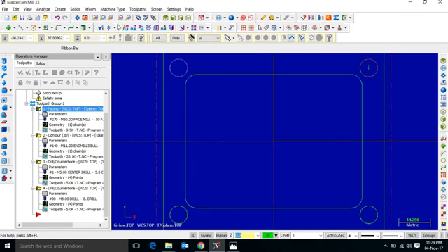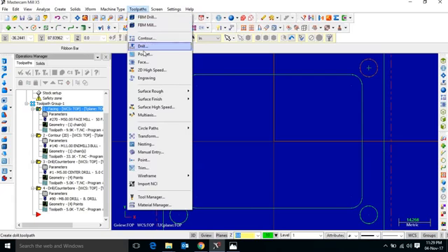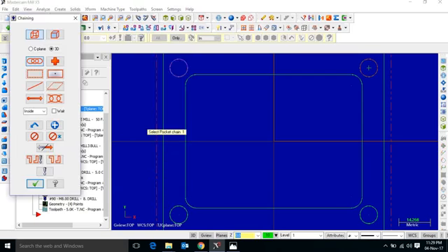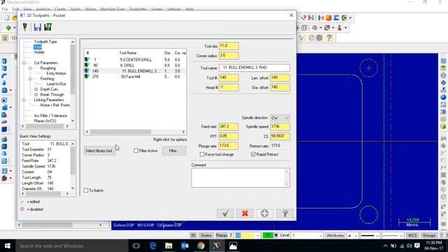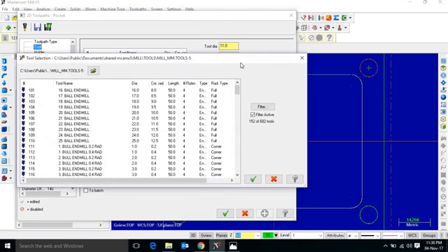So now top view, toolpath, we have to use the pocket operation, pocketing this rectangle to 5 mm depth. Select the rectangle, click on OK, and we have to select the 3 operations. First one is tool, second is depth of cut and third one is linking parameter. First, select the tool. Now while selecting the tool we have to consider one thing, that there is a 5 mm radius fillet at each corner of the rectangle.